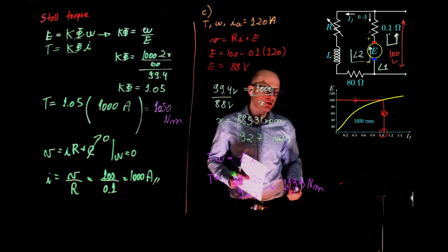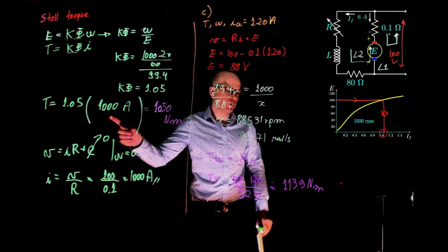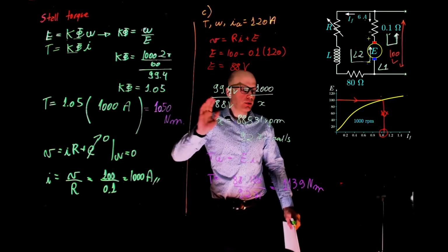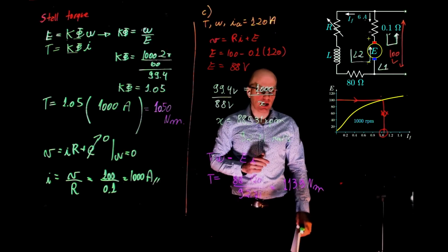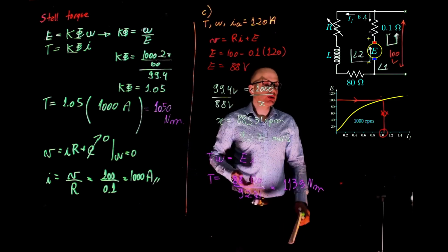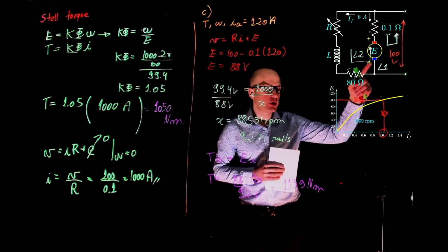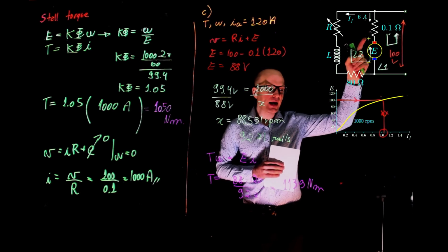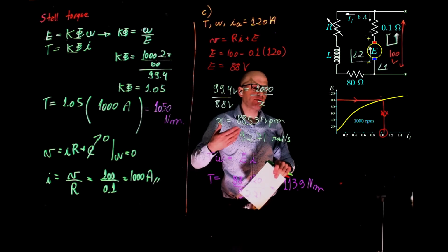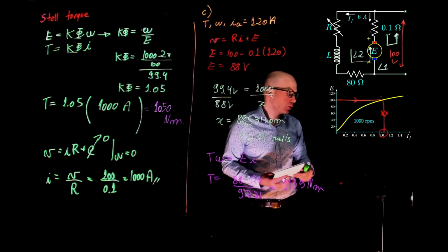Of course, this torque is much higher than the nominal torque. We notice here that 1,000 amps is also not trivial to deliver to a motor. The motor will probably burn down in a few milliseconds if this stall torque is sustained. But as the motor starts to rotate because there is a torque, there is a back EMF, which will oppose this current. As it opposes, the current drops, and so does the torque. Eventually it reaches a steady state at the nominal torque if left to run at no load.